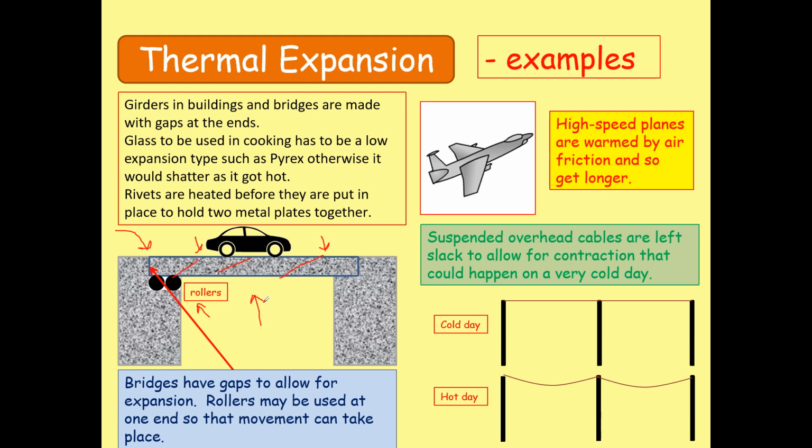So that is why you will always find either bridges having these metal bars, or if it's a stiff bridge without these metal slits or gaps in between, and if it's a small bridge, then you will find there are rollers as well as an open end at one corner of the bridge, which will allow this gap to have the expansion, right?